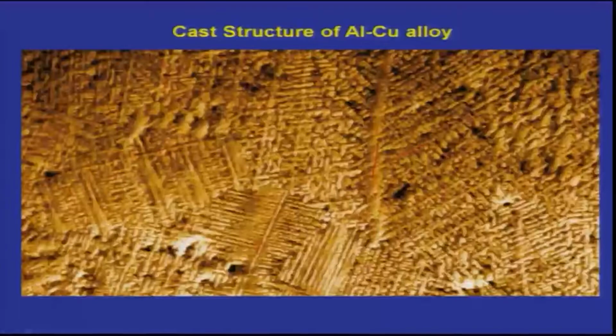Basically the way we show the microstructure is by using an etchant, or some etching process. Etching means we use a chemical, either an acid or a base or something, to react on the surface of these alloys or metals. In pure metals normally the reaction will be uniform, but in alloys the reaction will be preferential. Some elements will react more strongly than others, and because of that it will leave the structure nicely revealed under optical or SEM microscopy. In a pure metal also dendrites are seen, but they are known as thermal dendrites,